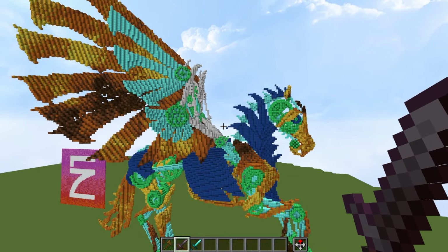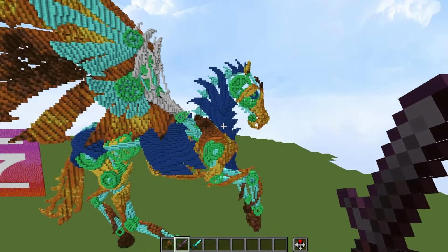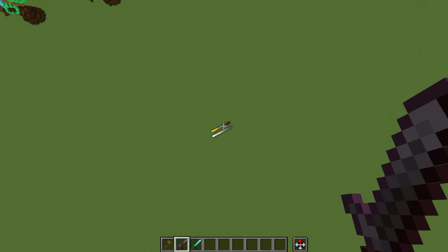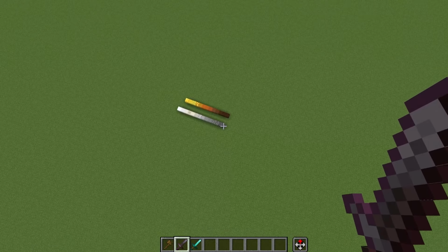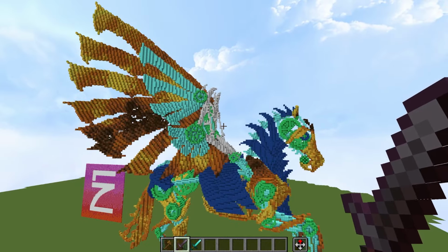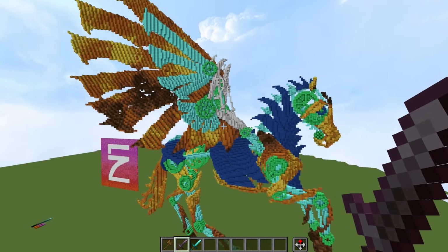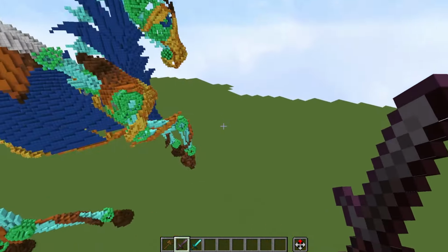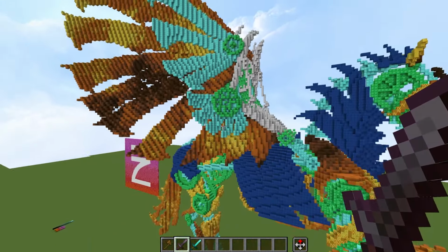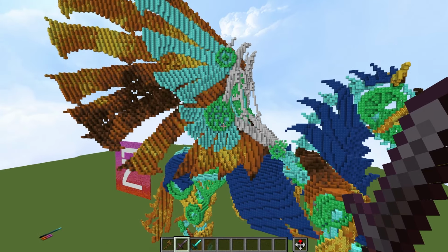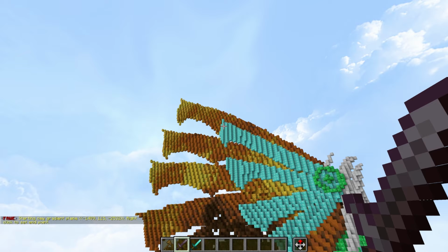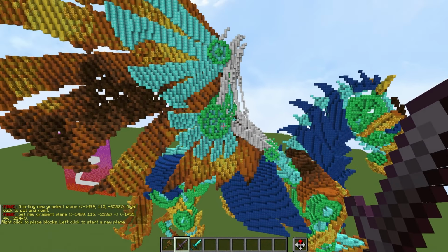Now remember, I have my gmask set to diamond, and I'm not sure exactly which direction this gradient is going to go, if it's going to use the darkest gray as the second point or the first point. So I'm just going to try it out and see which direction it's going first. So let's say I want to do this piece of the wing separate from these other pieces, and I want this part here to be very bright, the bright white, and I want to go into the gray down here. So I'm going to click one point up there for one end of the gradient by left clicking. Then I'm going to right click down there.